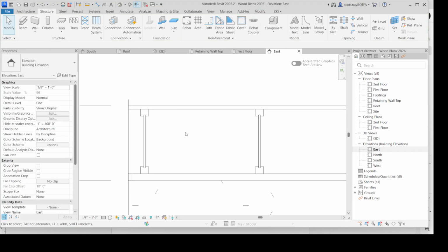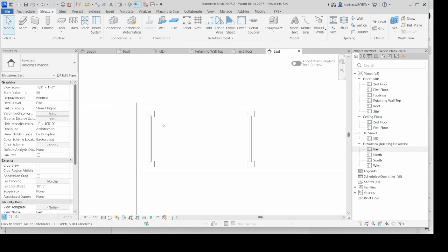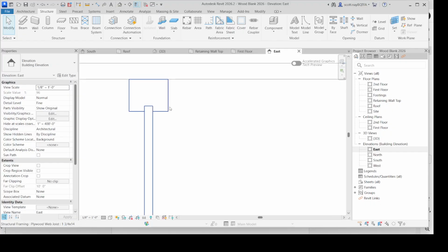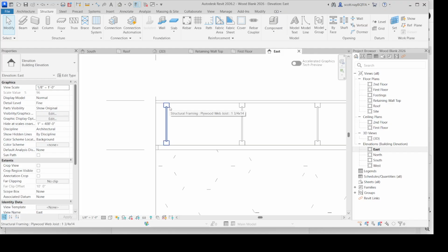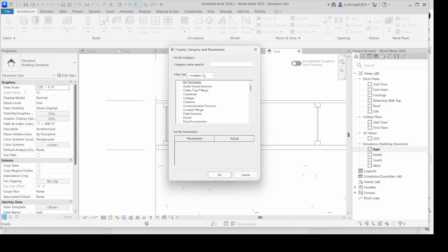So I'm going to model insulation as a component model in place. I'm just going to do a regular rectangle. Some people last semester wanted to cut in and get right up on this. Especially if you're using rigid insulation, I don't know that anybody on a job site is going to sit there and carve out this. Maybe if you were using rock wool or something like that, you could have it be wider and you just kind of cram it in. But I'm going to keep it simple. Go with a model in place.